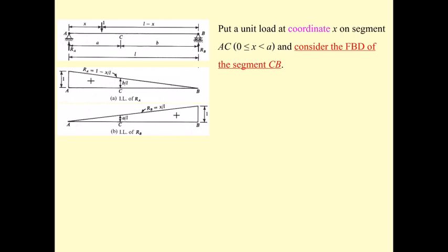And the concept, as you may notice before, is that when the force is in some area, for example, if the force is in this region, it's going to be as shown before that you are supposed to use this portion of the free body diagram to compute the shear force and to compute the moment.